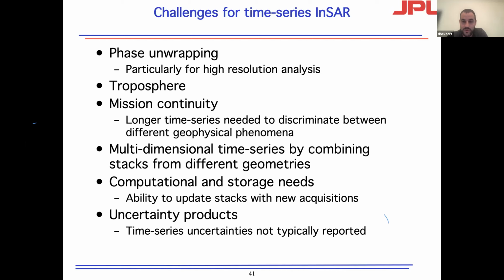So ionosphere could contribute to a phase unwrapping error potentially if you have some of those streaks in the data. So it could be a cause, but it doesn't need to be the only one. Probably decorrelation generally is the main challenge. You also have other superimposed components like troposphere, which could cause an unwrapping error. So the closure is really looking at the unwrapped data and making sure that it is consistent for a triplet.